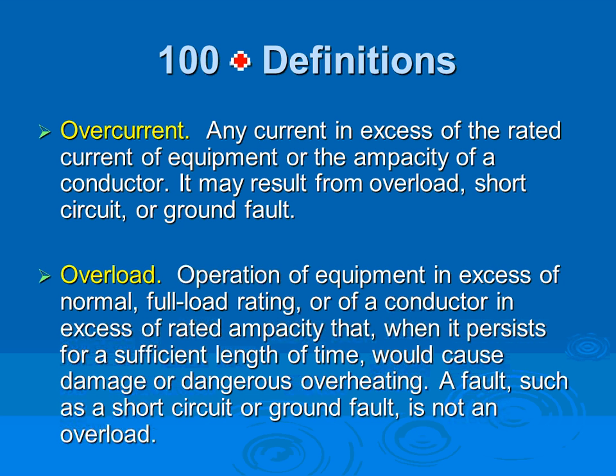Air handling units and chillers and so forth. They provide extra, they separate the overload from the short circuit and the ground fault. That's why we stick that electronic overload protection or thermomagnetic overload protection. They separate it because of the importance of the load.